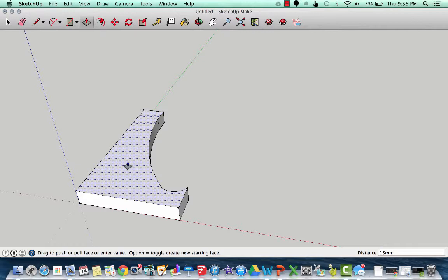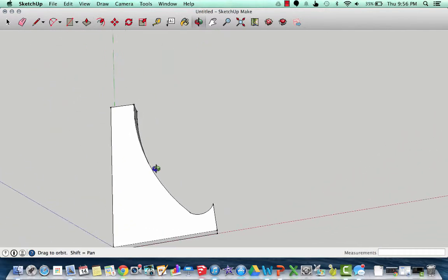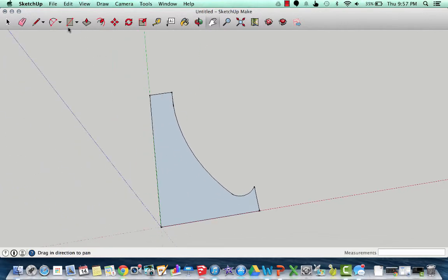And you could type in 15 and get something perfect, but in this case, it ended up working out pretty well. Now, very cool stuff. This is done. The problem is that it's going to take up a lot of ABS or whatever type of material that you're using, and a lot of it's wasted. It's unnecessary. All of the content inside here is unnecessary. So what we're going to do is I just Control Z, undid that. What I'm going to do is I'm going to actually clear out some of the unnecessary pieces.